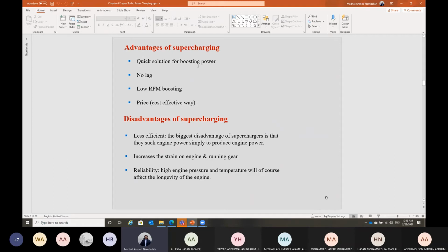So usually, if you have your car equipped with a supercharger, when you press the accelerator pedal to increase the power, you will find the engine responding a little bit faster than in the case of a turbocharger. Because a turbocharger takes the power of the exhaust gases, converts it in the turbine into power for the compressor, and then the compressor can compress the air.